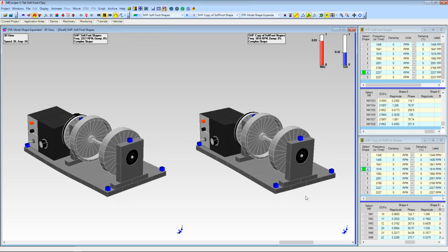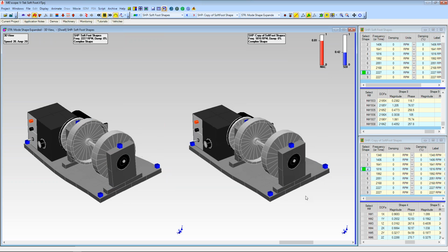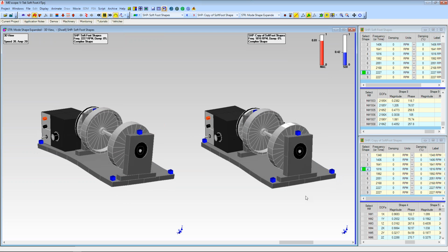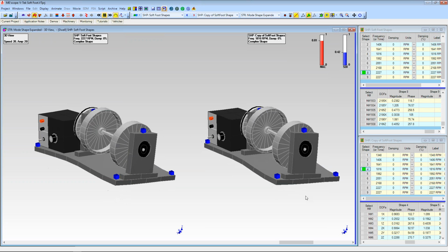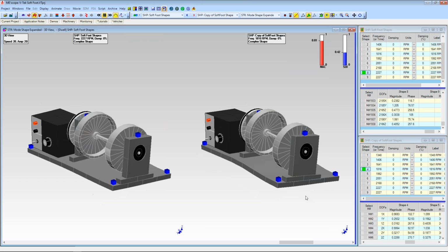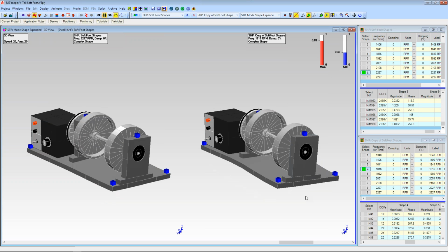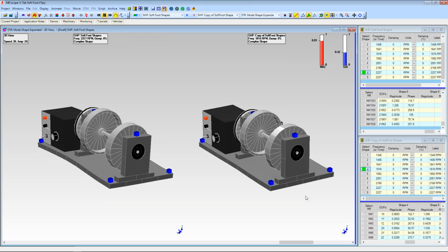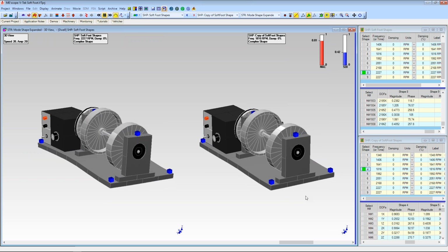We covered a lot of material today. We covered facts from the archival database and the console use. We've used that to detect and diagnose unbalance and misalignment. And we looked at using different acceleration data from the motor and bearings versus the base plate.